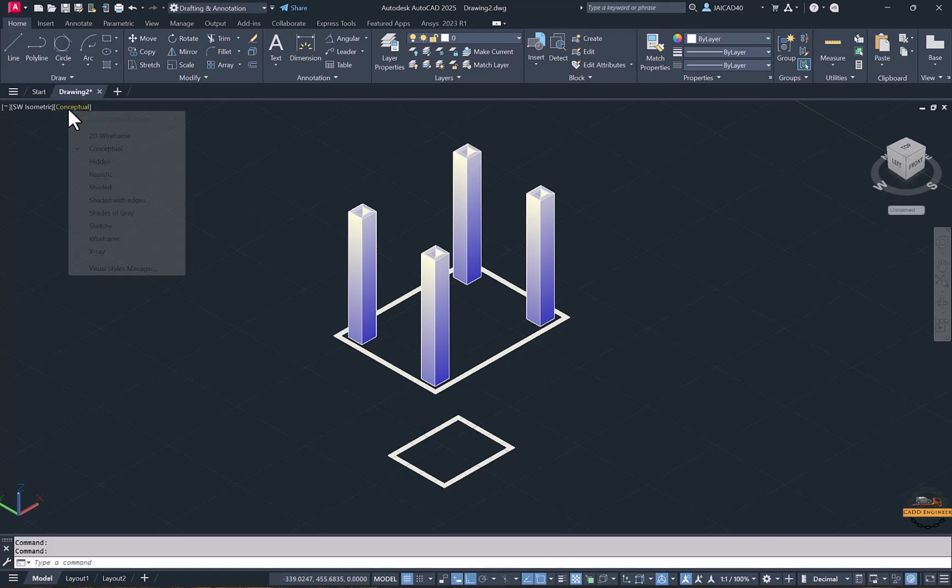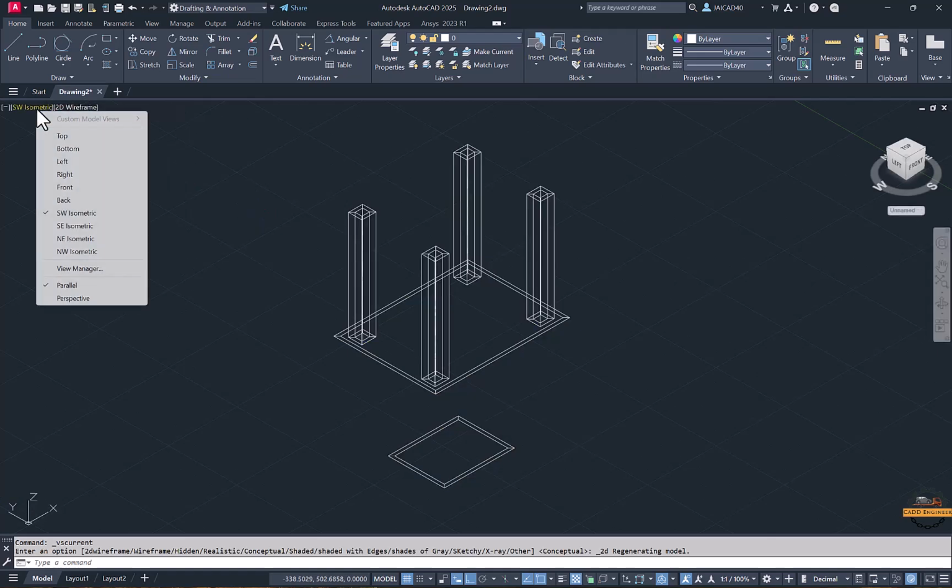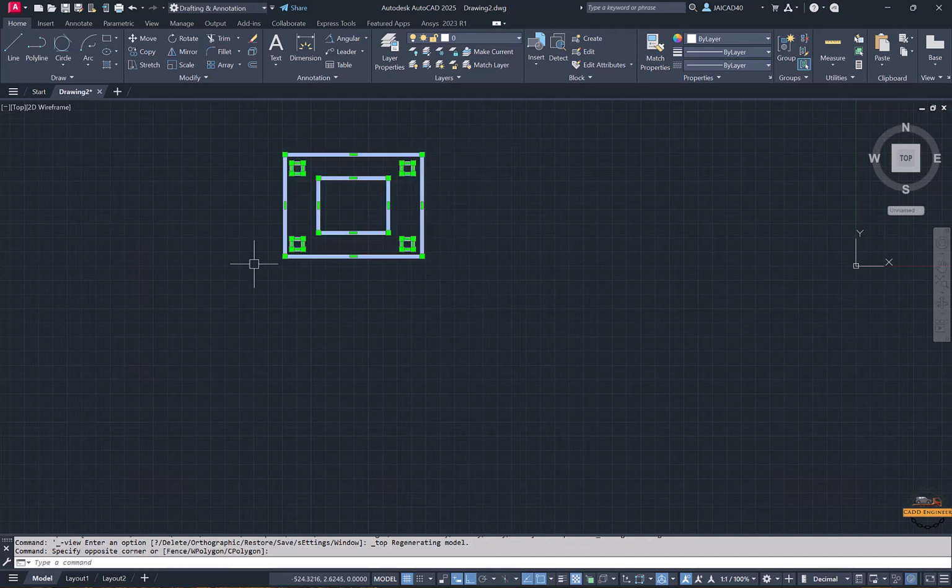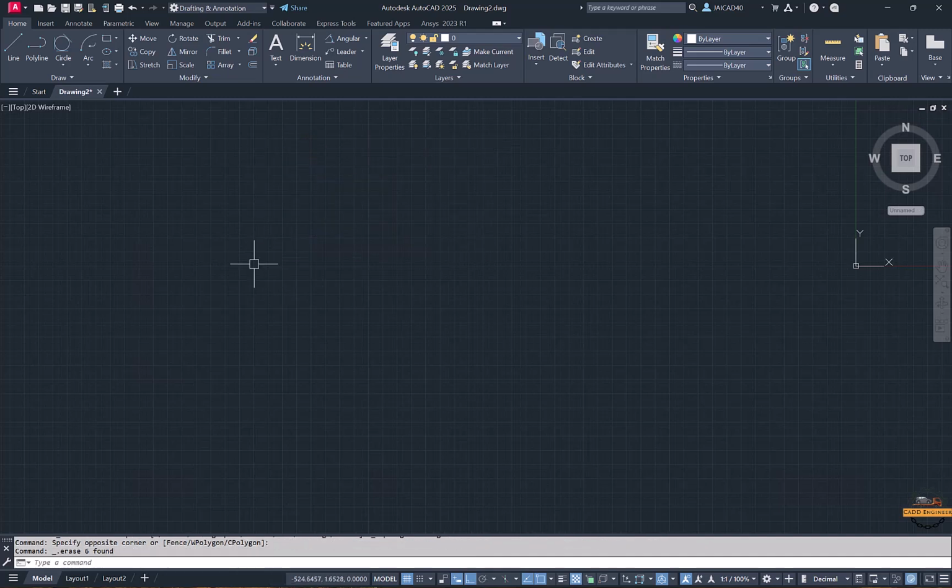Now let's get back. Let's go to 2D and top view. We'll delete all this. Now we'll see something more in the rectangle. I'll go to REC enter. We'll click. Okay, we don't need this thickness and all now. Let me make it 0. Width to be 0. Thickness to be 0. Elevation to be 0. So whatever we had taken previously, we can make it 0.